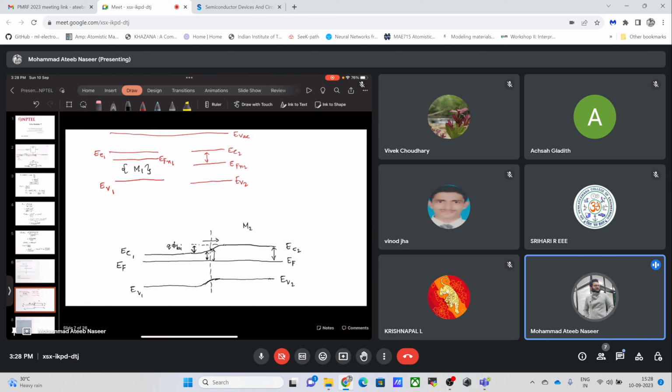But let me ask you one question. If I am having, for example, this kind of doping, N_D, which is constant in x, what do you expect? Can you infer anything about this band bending? How would it behave? What would be its function of x? Would it be a linear function in x? Would it be a square function of x, considering this to be constant?